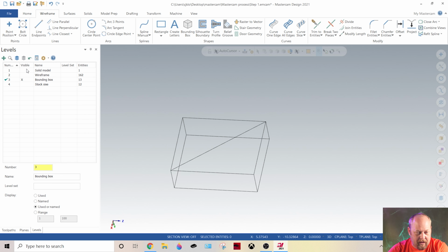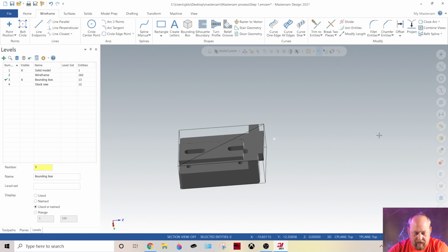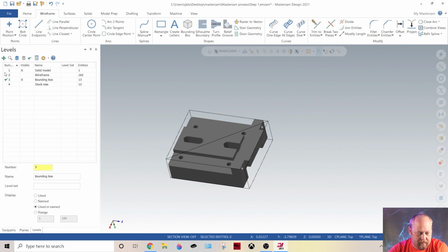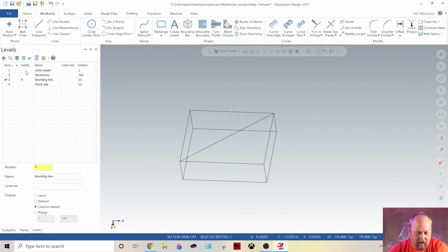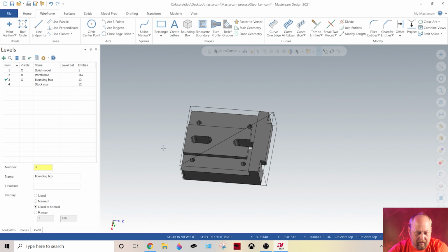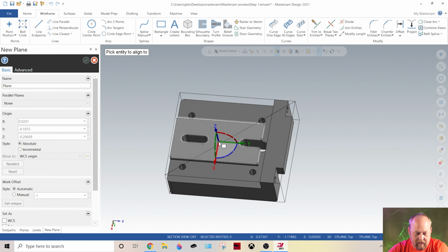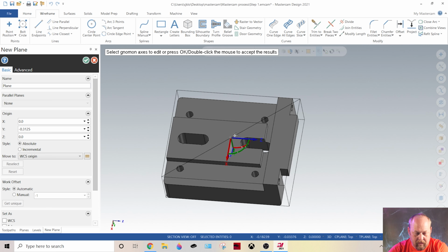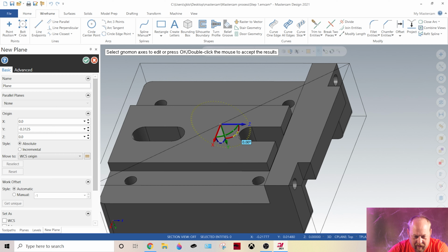I draw these lines right here when I want to pick up on center line. It looks like we're only going to pick up on center line on that side, so I'm going to make that line just for that sake. I'm going to turn my solid on, my wireframe on, grab this, and hover it over so it grabs that middle line. See that? Boom. Now grab the little tiny inside one, it's got to be the middle one. You click that, and you rotate that up 90 degrees.